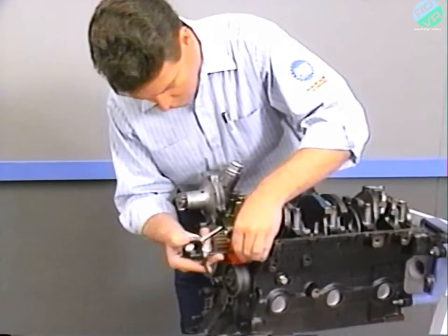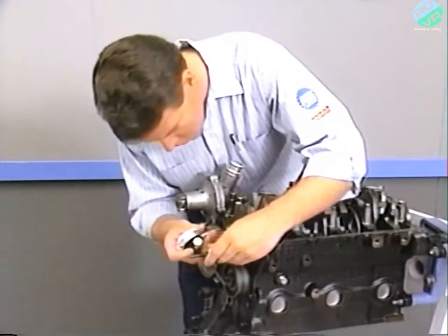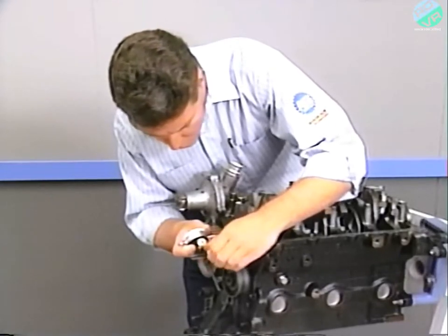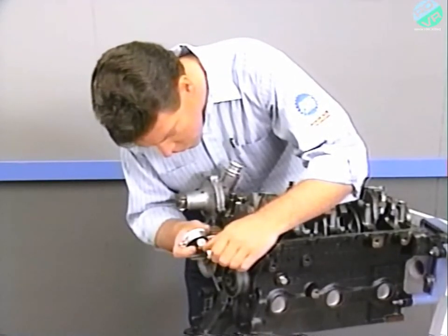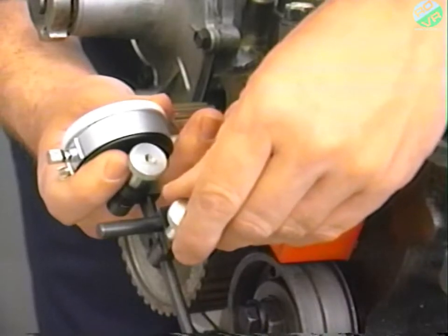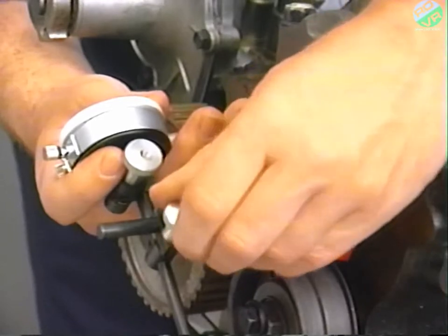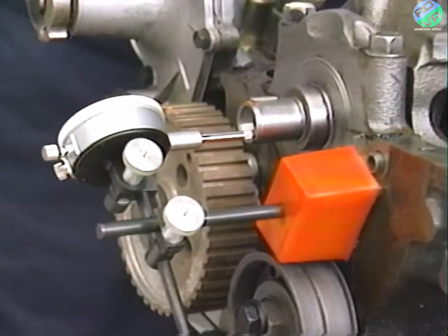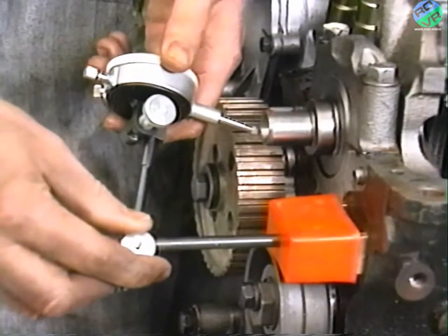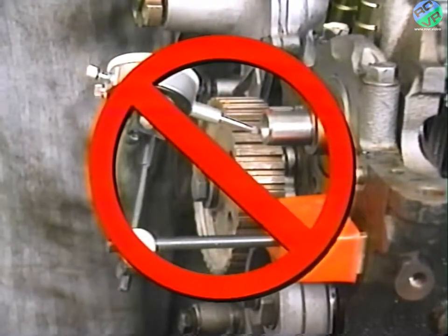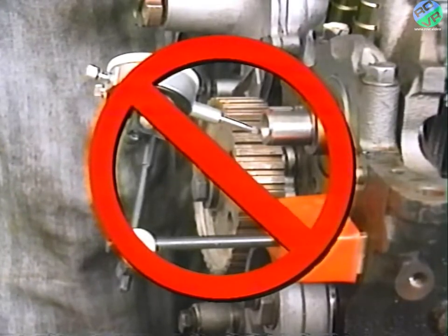When using a dial indicator, make sure that you mount it to something firm, such as the engine block, rather than the car body, which can flex and cause faulty readings. Keep the support arms as short as possible for a rigid mounting. It's also vitally important to make sure that the indicator is set up exactly perpendicular and parallel to the center line of the shaft. In this case, the indicator is not set up parallel to the workpiece, giving a false reading for crankshaft end play.